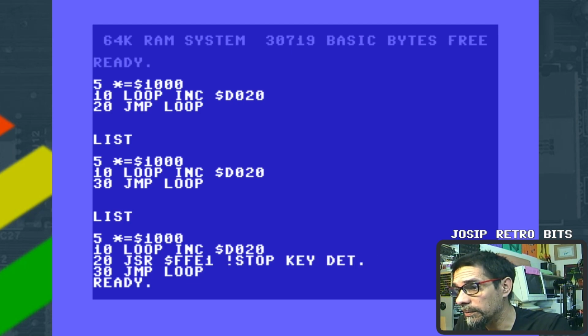detection subroutine. In case we press the stop key on the keyboard, the way the information is transferred, how we can use it, is that the zero flag is activated in the status register, and in that case we can use a branching instruction here, which I mentioned before, which is BNE.